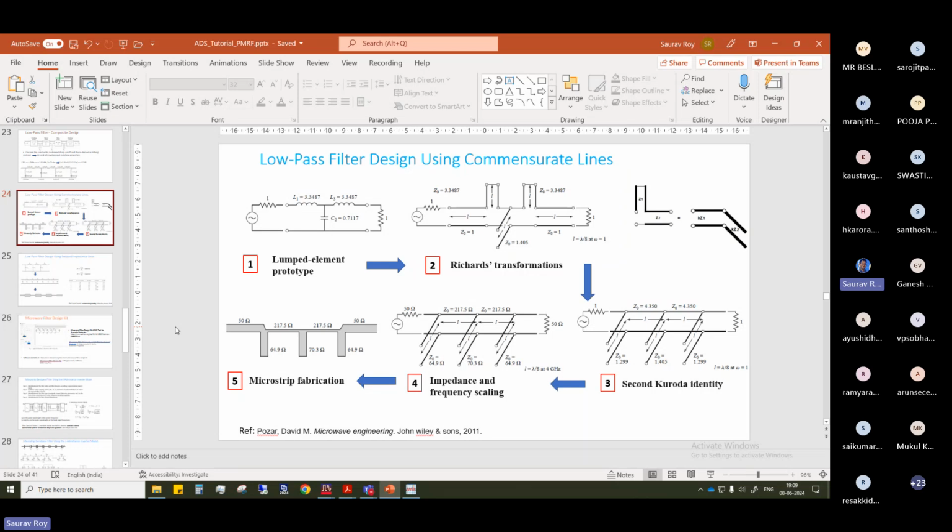Yes. I mean, you tell me in which of these steps you are saying that it is not required. Which step? In 1, 2, 3, 4, 5, which one? No, in a simulation, first we are going to the schematic. Then we are taking the available transmission lines. There we are putting impedance, these and all. Then we are converting into the layout. So since we have an impedance and trace width.